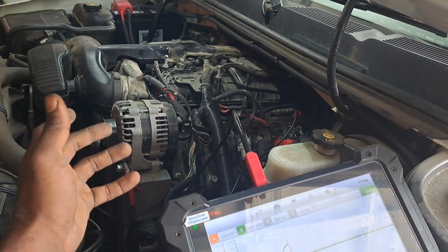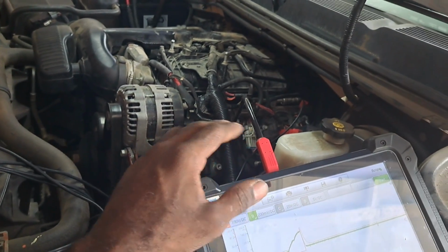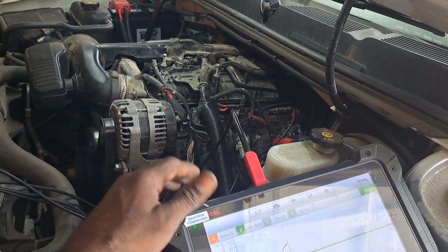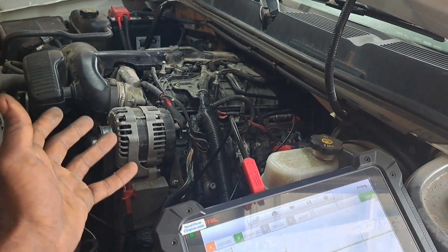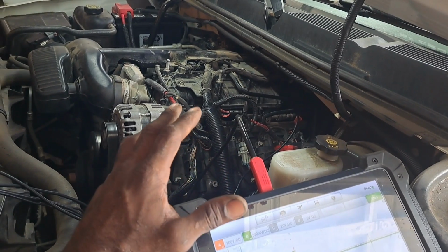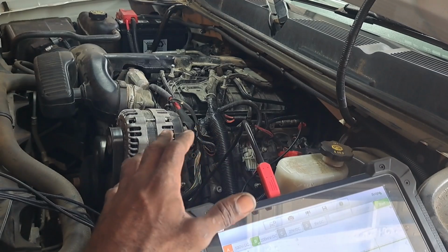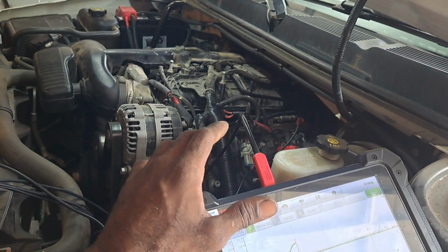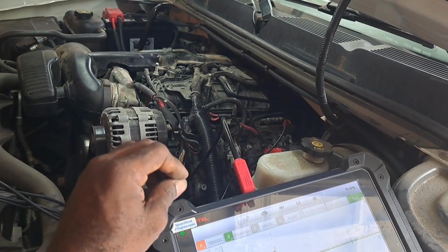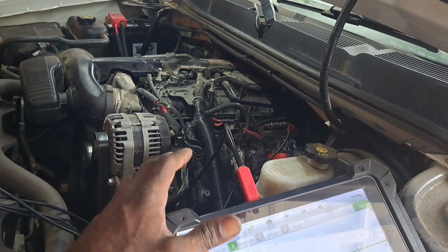It happens. So when I pull these injectors out on bank 1, I'm gonna inspect those and see if maybe there's some debris. It could be a spray pattern problem, you know, atomization. And again, I'm not dealing with any intake leaks or anything, but depending on what conditions aren't satisfied, and being that the description said it was picky, this is probably what we're dealing with. It just needs some uniformity across the board, and we could have a bad injector failing under the right circumstances.